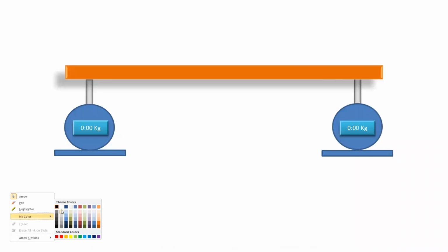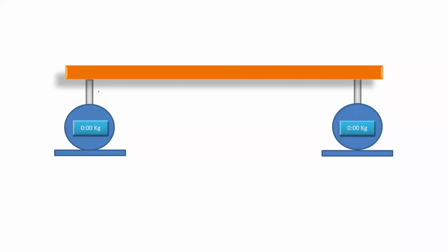And this is your experimental apparatus. Here, this is the beam. Actually, this is a wooden beam, and this wooden beam is supported at its two ends, A and B. Now we have to find out the reaction at its two ends, experimentally. So we have connected the spring balance. This spring balance will give the direct value of this reaction in kg or in gram.